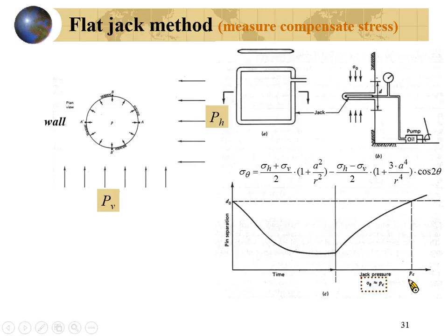When you make the measurement, you will try to measure the stress at the tunnel wall and on the roof of the tunnel. Then what stress do you measure? If we call it the compensated stress, PC, actually this PC will equal the sigma theta.